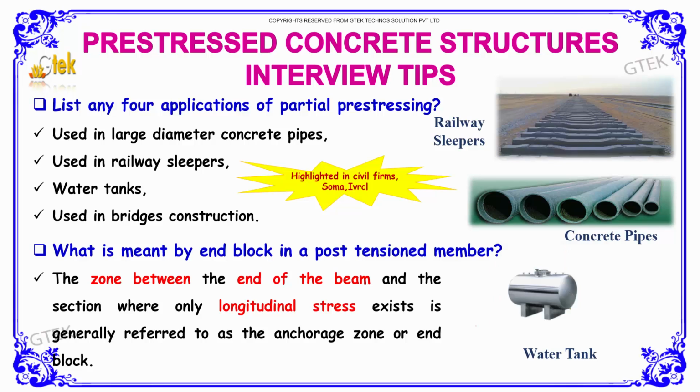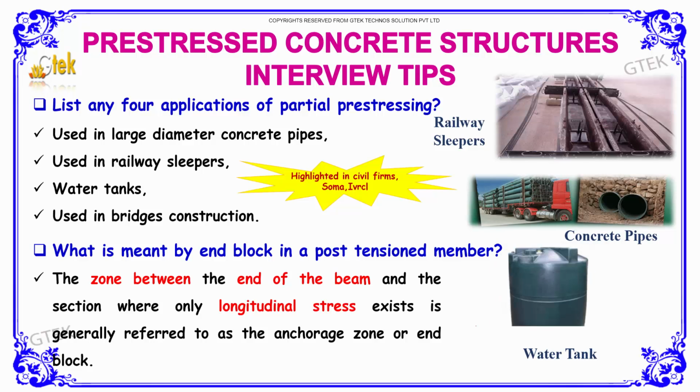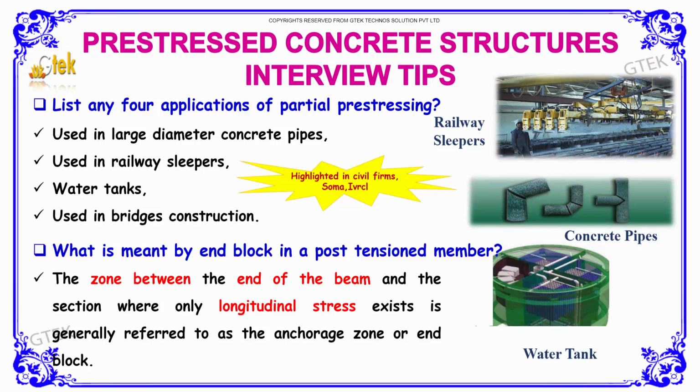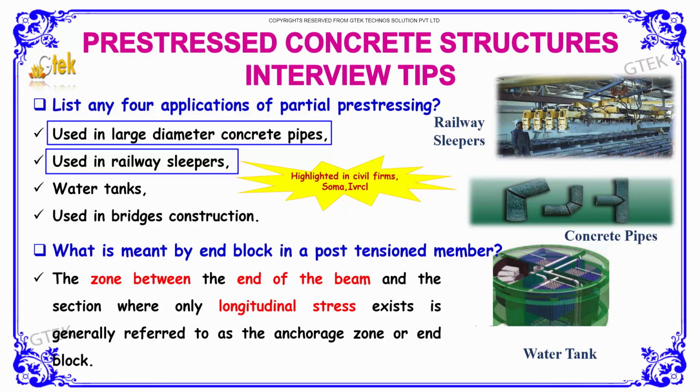We got the next question. List any 4 applications of partial pre-stressing. The 4 applications are as follows. The first one is large diameter concrete pipes. The next one is railway sleepers. The next one is water tanks, followed by the final one, bridge constructions.